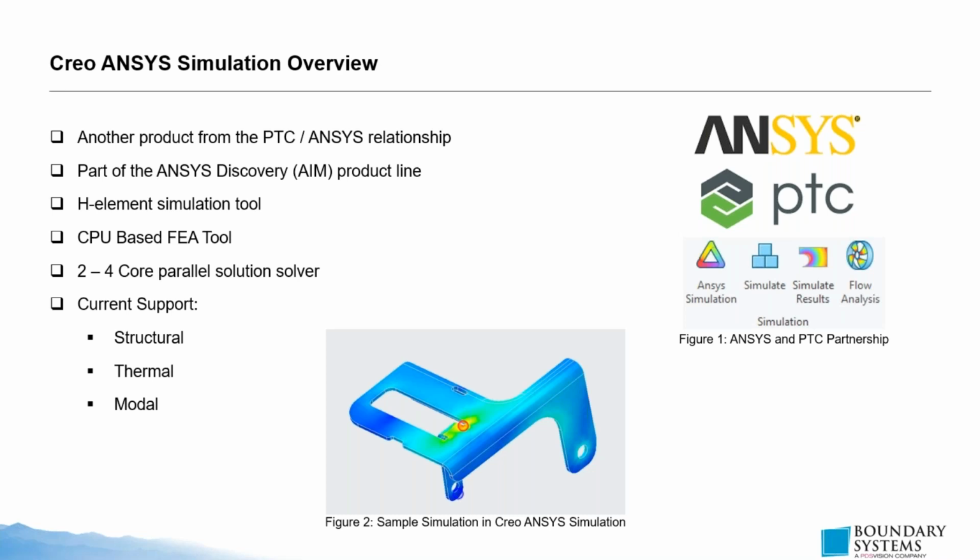It's part of the AIM or ANSYS Discovery product line. You may not know, but ANSYS has many product lines within the ANSYS family. This is part of the Discovery product line. This is an H-element simulation tool. The other tool for FEA in Creo is Creo Simulate. That's a P-element tool.